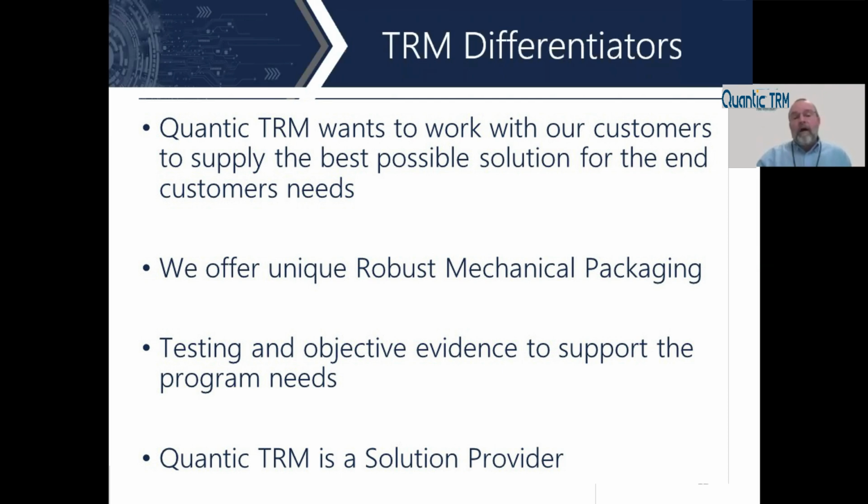Yeah, one big thing that TRM does is that we build these products using a wide variety of technologies. There is no one technology that is better than any other. For example, if you're looking at a lower frequency part, then you're going to want to use a wire wound ferrite-based technology. Getting up to higher frequencies, you're going to want stripline technology. One of the advantages is that TRM uses all of these technologies, with the exception of waveguide, to build these devices.